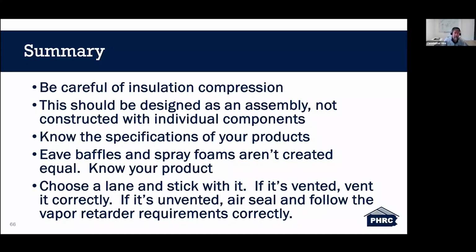Know the specifications of your product. They're not all created equal, as shown in bullet point number 4 here, right? You know, not all insulation is created equal. Not all spray foam is created equal. Make sure that you don't just call it spray foam insulation when you specifically need a closed cell or something that's a class 2 minimum vapor retarder, right? So not all spray foam is created equal. Make sure that the spray foam that you're anticipating being used, you specifically called out.